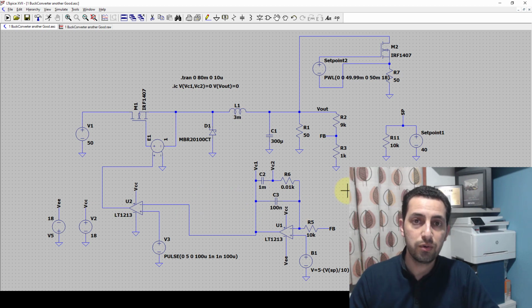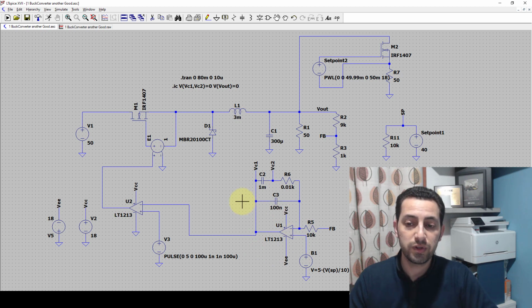Now, usually when you try to find a feedback system for a buck converter, they share this network as a feedback system. Very rarely do you find a different network from this one, because this one is simple, and also the LTSpice simulation is fast considering this simple circuit, rather than choosing to do it with multiple operational amplifiers, for example PID control or others. They consider this one just to speed up.